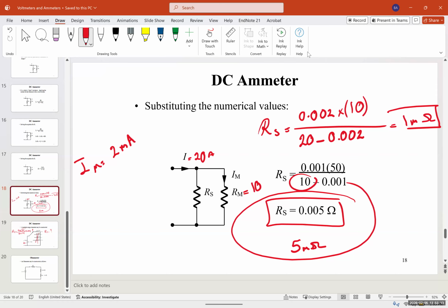There is also a way to calculate VM: we usually give it a very small voltage without RS, and we measure that VM. But usually on these multimeters, if you look at the data sheet, they will give you VM and IM for different voltages. It's a little different, so if the voltage increases, the VM increases a little bit.